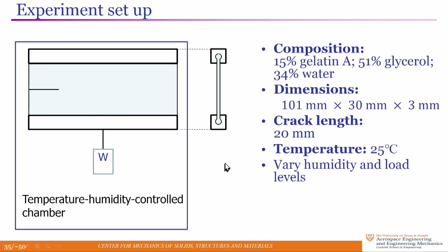So first, some experiments. This time we use what's called a simple shear experiment for strange reasons. But the idea is you take a strip of this material, clamp it between two rigid boundaries and displace them vertically, insert a pre-crack in there, and then let this thing do whatever it wants to, diagnose it, and figure out what you did to it to extract fracture properties. What we did was, instead of driving it at constant rate, we applied a constant force on it so that the process would be one of creep, viscoelastic creep, and then poroelastic diffusion.